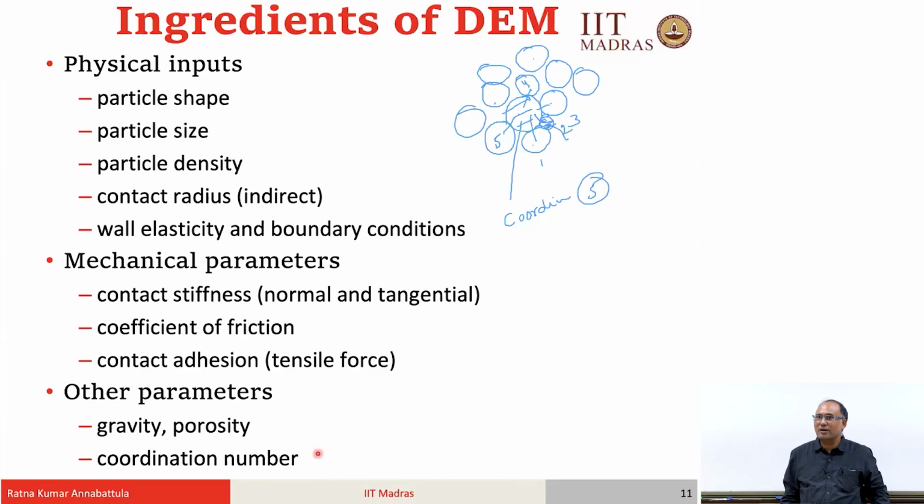Sometimes you will see that, for example, if you are transporting vegetables, like tomatoes, right. If you pack them, typically the bottommost tomatoes are a little bit more crushed compared to the topmost ones, right. That is precisely what you are expecting. In silos what happens is that there will be an arch formation, and the force distribution is such that an individual particle is not experiencing that force. You will not be able to see that unless you have a mechanism to represent this arching behavior. So, that is where the macroscopic constitutive response is changing, right.